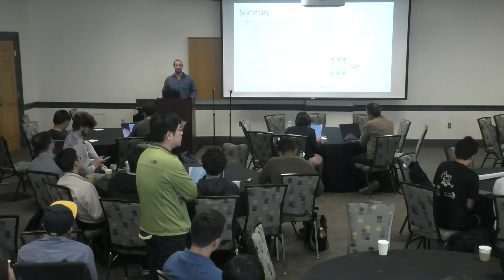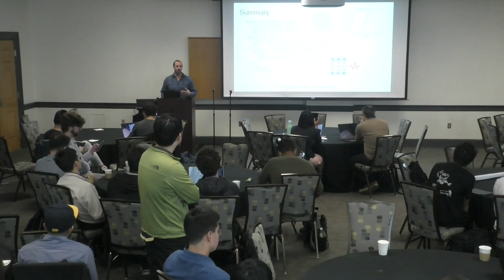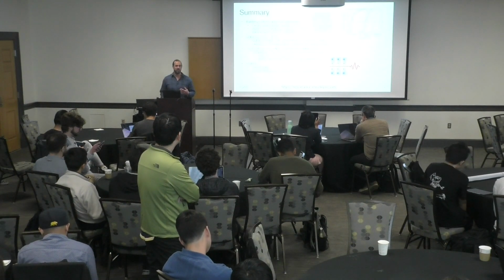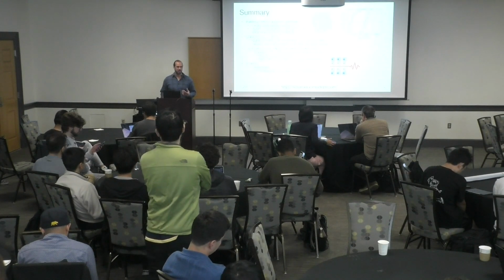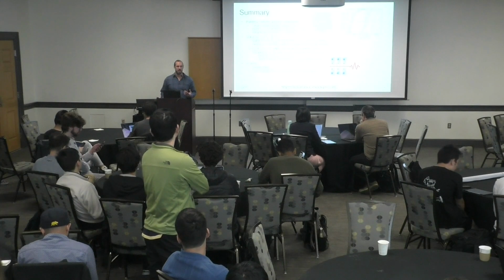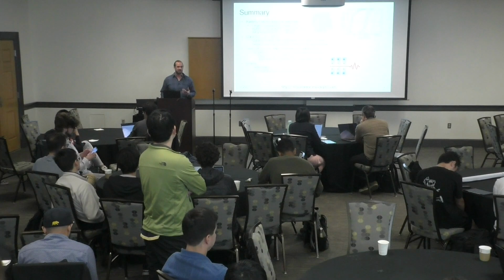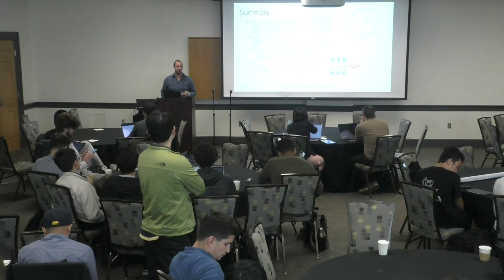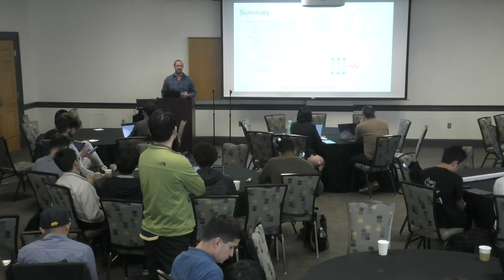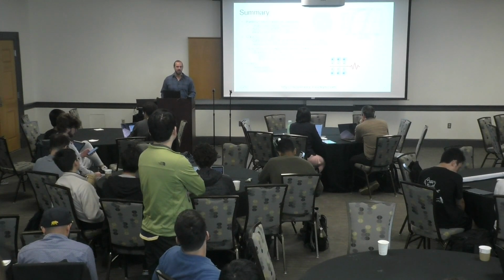Yes, the short answer is yes. You have the ability to tune the frequency of the qubit and control the interaction strength. One caveat is you can only tune the frequency of the qubit down. For most of our devices, the qubits have an anharmonicity of about 100 megahertz, and we are targeting a maximum frequency of around 150 megahertz above the resonator. So if you wanted to be far detuned, you would need to tune the qubit down in frequency quite a bit, which would move it away from its flux insensitive point and decrease its coherence.